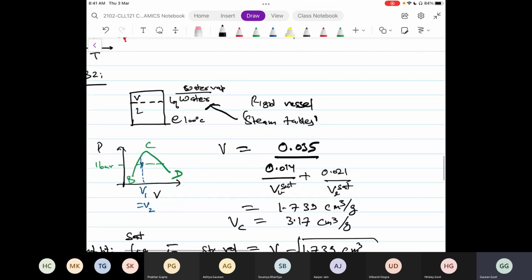But when I store liquids, I make sure that this empty space, or vapor space, is sufficient that whatever heat gets added because of storage conditions will not lead to complete removal of this vapor space. Maybe I start with 20% vapor space. During the day, some heat gets added to the system, and that portion shrinks from 20% to 2%, 5%, whatever is my design constraint. Okay, but I make sure it doesn't shrink to zero. So that is up to my design.